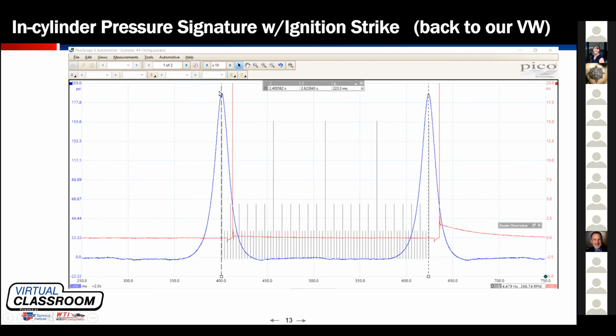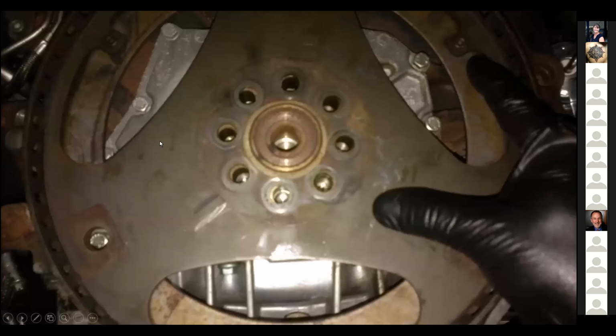But the dude in the dash thought it was over here. That's got to lead you, guys, to only one sensor on the car. What one sensor on the car could be misconstrued and make the dude in the dash think the piston is in one position when it's off by a creepy factor of like 45 degrees? The answer in this case was that the reluctor ring had been installed improperly on the back of the crankshaft. And yes, this crankshaft reluctor ring, guys, is the flex plate.